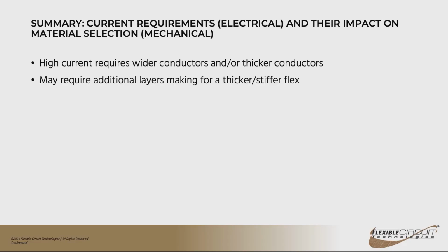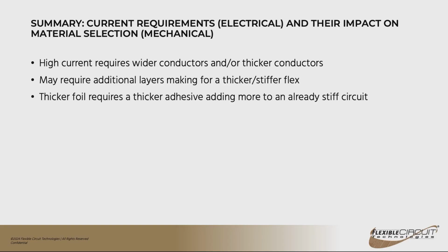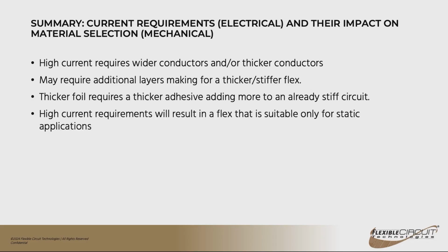It's going to require possibly additional layers, making the circuit thicker and stiffer. And thicker foil is going to require additional adhesive to encapsulate the conductors, which is going to make it even more thick and stiff. And what you're going to find is high current applications typically result in a flex that's only suitable for static applications, where it's a flex to install and isn't required to bend and do a lot of additional dynamic movements after it's completed.